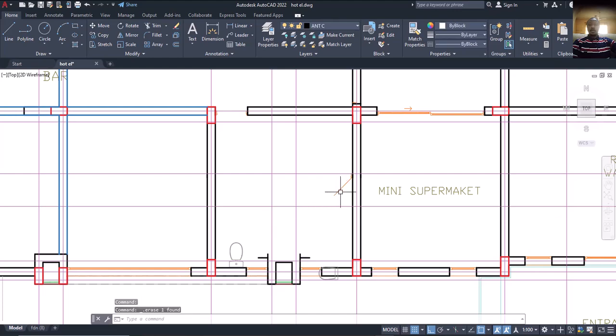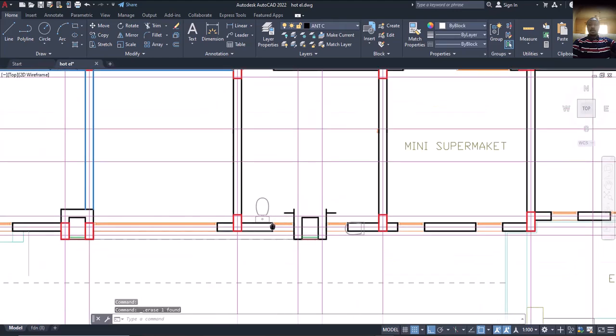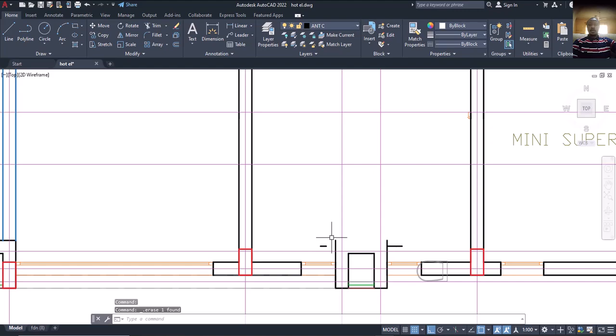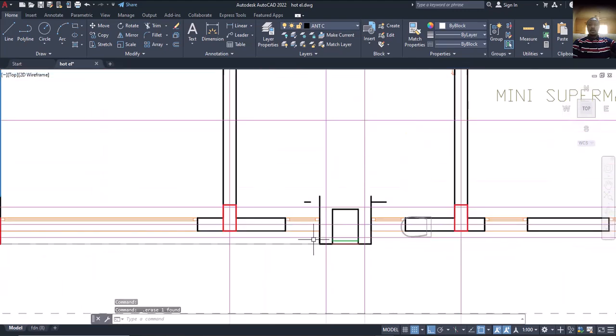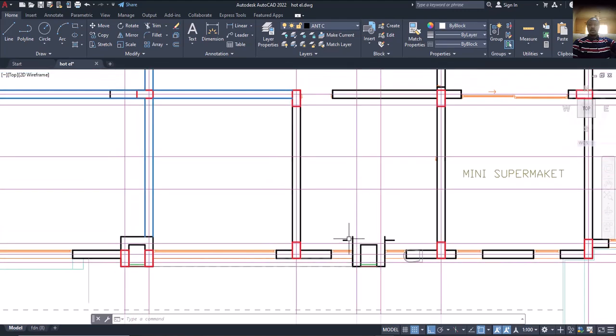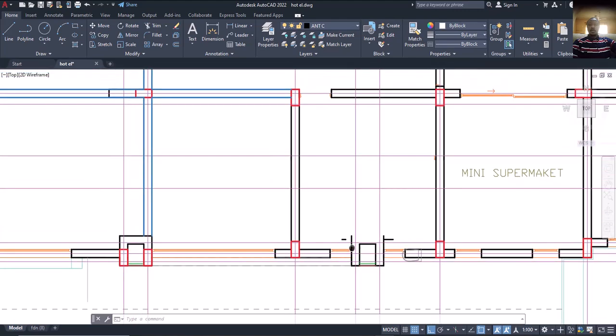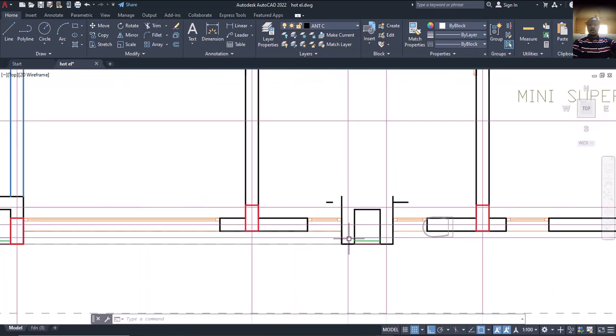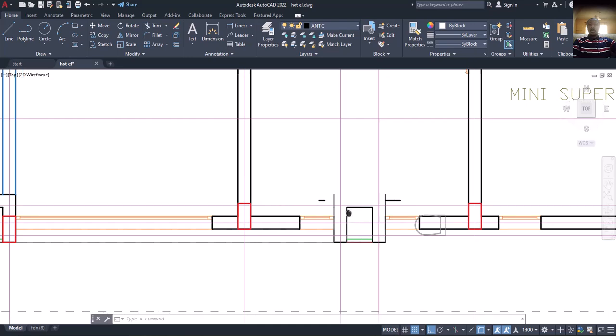You can see what we are doing. So this is how you go about it. Then this one, remove this one, remove this one, because I'm going to run my beam all through this place. Is that okay? I'm going to run my beam all through, because if I want to put another column to form this shape, it will not be too nice. We're having too much of columns around this place or this edge here. Is that okay? This one cannot come here as a cantilever. I don't want such. This one can be shifted. Is that okay? You can shift this one.